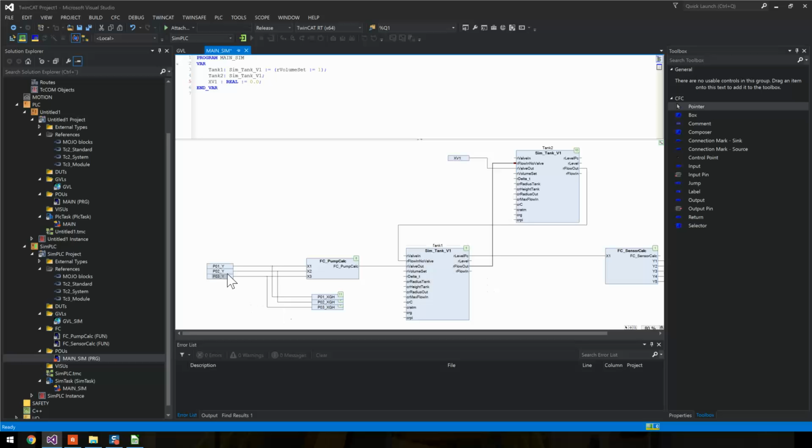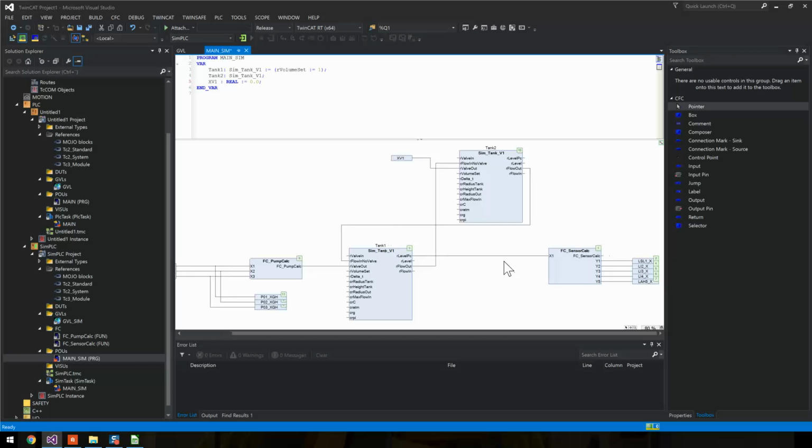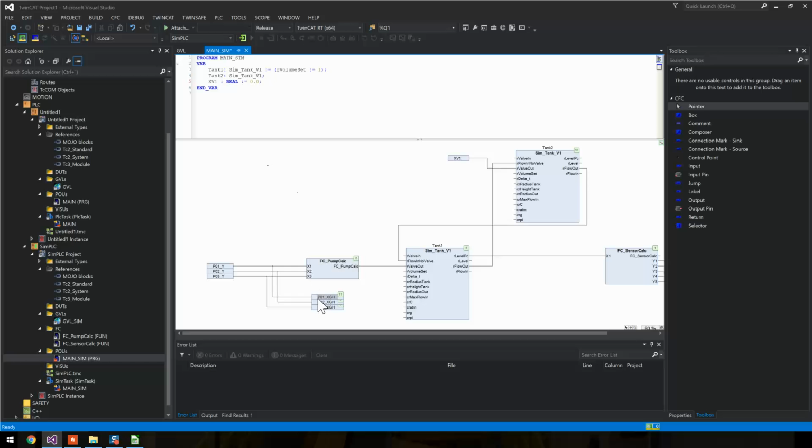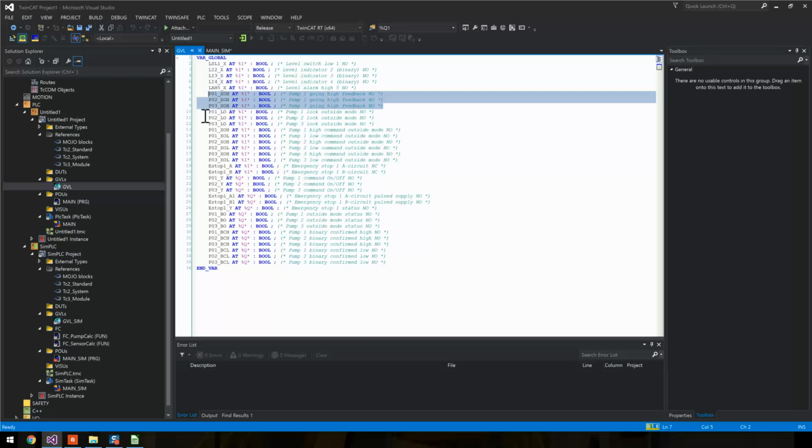And that means we've given the start command for pump 1 through our output card, from our output card through some other electronics to the actual pump, and the pump is rotating and moving water, and it's flowing where it needs to go. That's a better running confirm than just confirming that the command was given. So that's those three. Let's see what else we can mess with.